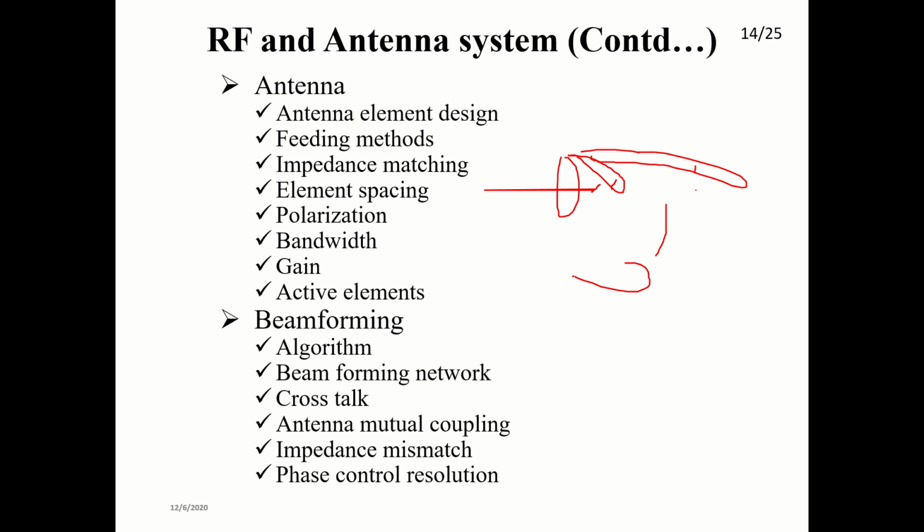Along with that, you have different kinds of beams, because you are not targeting only one customer. At the same time, you will be targeting another customer who is stable also. One customer is roaming in a bullet train, another customer is sitting stable here, another customer is slowly moving in a car. You have plenty of scenarios. Therefore, the beam requirement keeps on changing, because a user is getting into a particular cell site, like not cell site, like 5G node B, under the coverage of a particular node B. So these are all the requirements we have to sense before we go for any design.